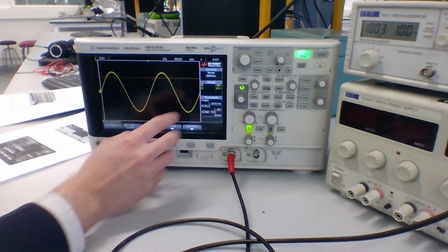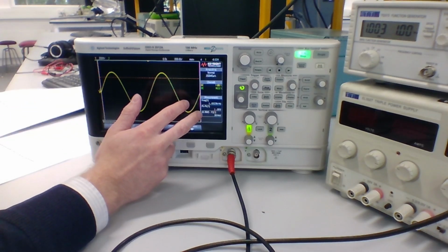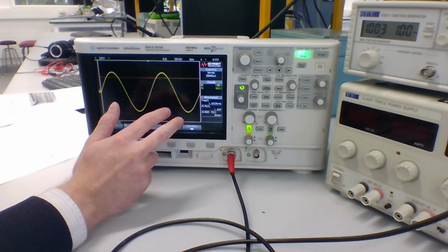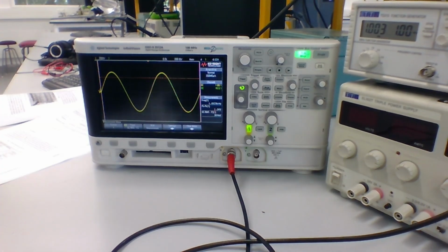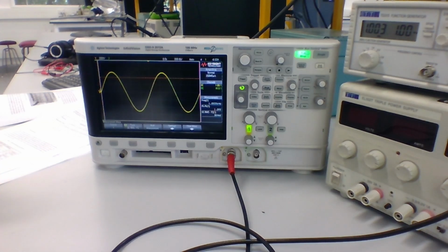Okay, so from that, you should be able to measure the frequency and peak-to-peak voltage being produced by the function generator as well, and take note of those in your lab manual. So you should note what the function generator is supposedly producing, and what the oscilloscope is measuring, and compare and contrast the two, and try to determine which is more accurate, or which you think is better, if there is a difference between them.